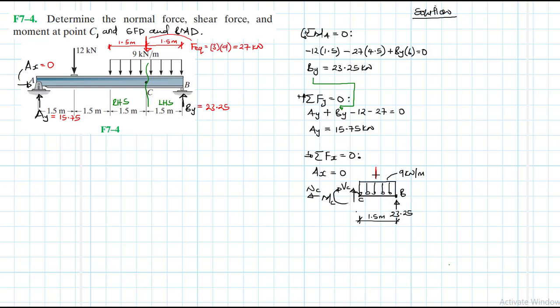Okay, so our equivalent force, and the length of this section is just 1.5 meters. And the equivalent force, of course, this is rectangular in nature. We expect it to be acting just at half the length, which is half of 1.5, 0.75, right? And this load again is just going to be equal to the area under the loading diagram. So let's call this F star, equivalent.